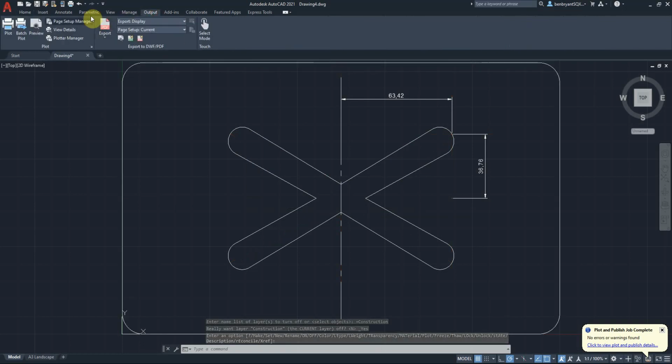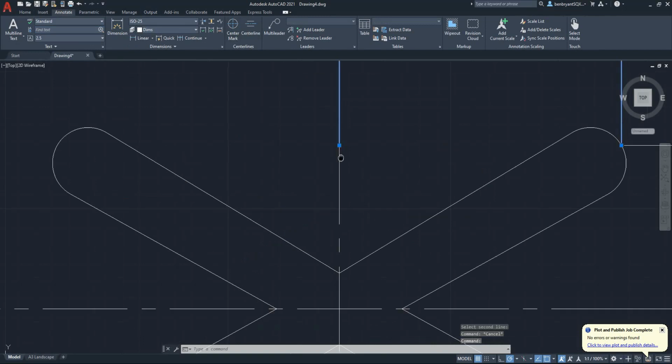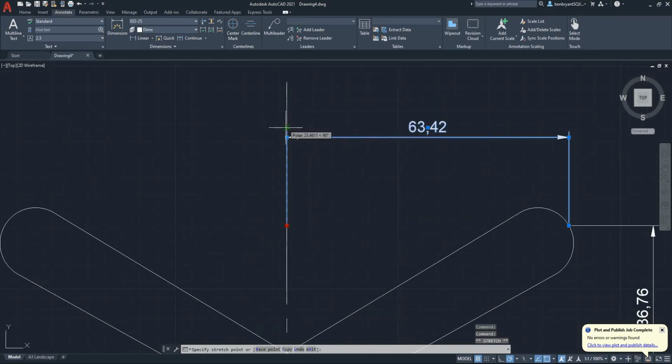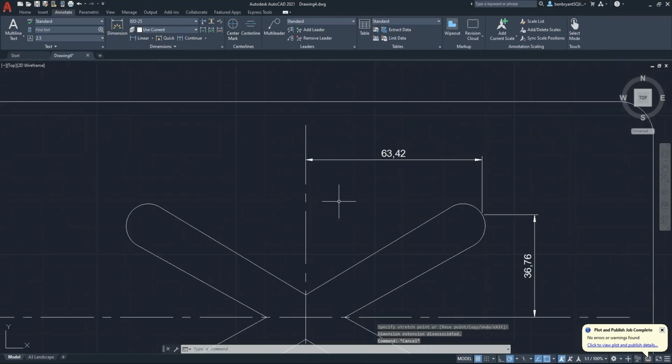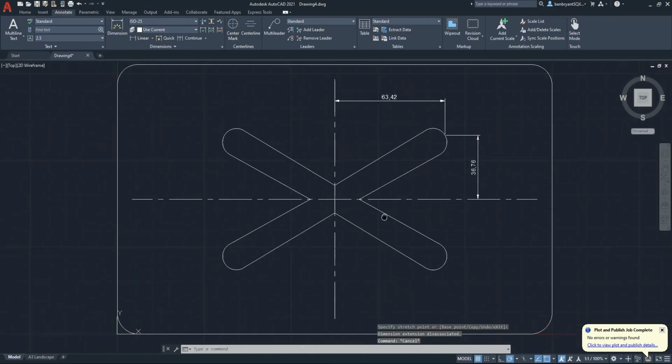Okay, output, so annotate center line top and bottom, like so. Now I'm just going to move that point there up to the end, so I get a nice arrow rather than having a big leader line, and the same with that one there. Just going to move on the snap point.